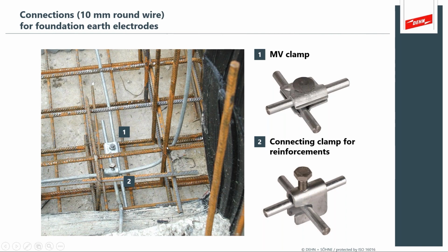One of the points I like to make when I talk to young people that are entering the industry is that you may know everything there is about concrete, but don't ignore bonding all that inner space steel. What might be manifesting as failure in steel in the concrete could actually be lightning induced damage, because your interconnected steel, these rebar members, are not actually bonded suitably for the purpose of controlling lightning currents.